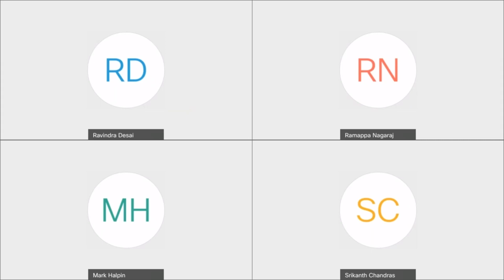Equipment vendors provide only magnitude of the harmonics, not the angle. Does the angle of the harmonic have any impact on the harmonic current TDD calculations and harmonic resonance? If they give the magnitude, that is sufficient. When they tell that the fifth harmonic is there, you assume that it is a balanced fifth harmonic. In a 3-phase simulation model, for example, 3% on 100 ampere fifth harmonic becomes 3 ampere.